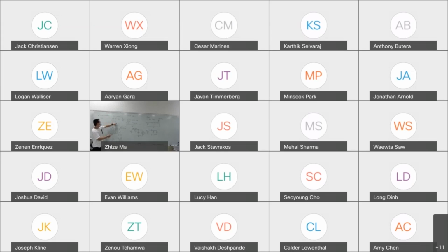And then the sine means that's the shape of your function. That means this is a sine wave, or sometimes it will be a triangle wave. You will need to draw a triangle wave. And the 100 here is frequency. Period is 1 over frequency. That's how you define the period, the time for one period.